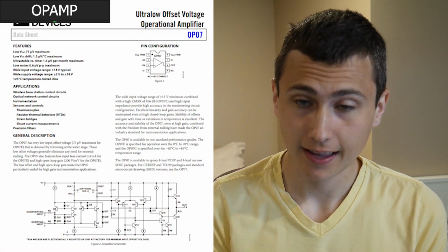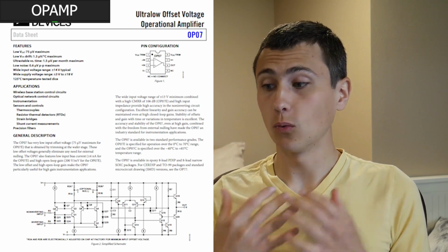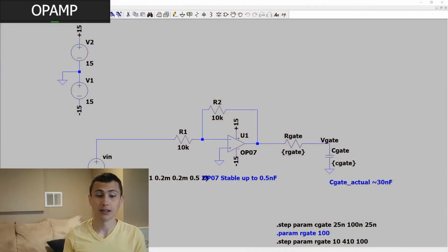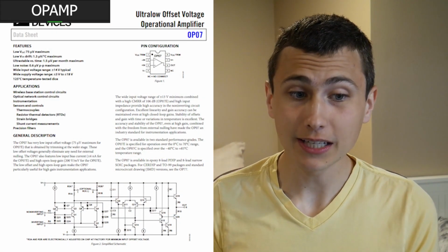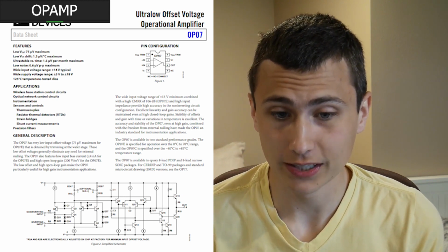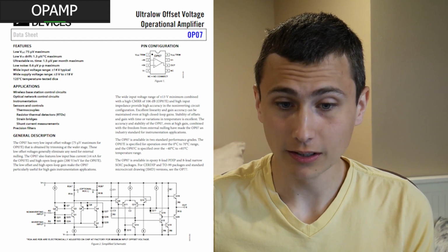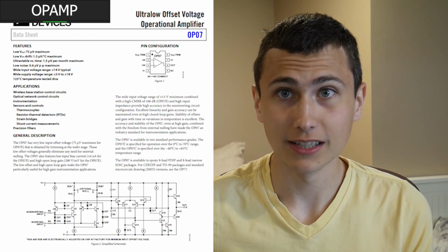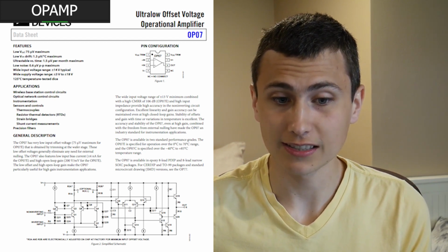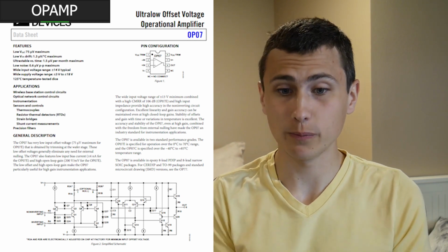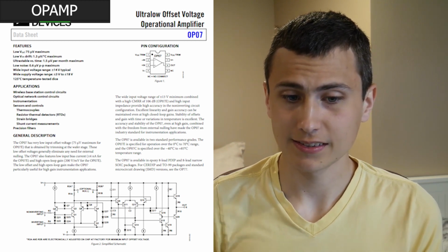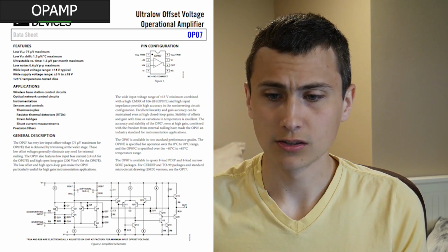The big deal about driving a part like this, you need to remember what we're driving it with, right? It's an OpAmp. It looks a lot like this. And basically what that means is there's a limited amount of output capacitance that we can drive. These parts become a little unstable. And by a little unstable, I mean very unstable. They start to oscillate if you put too much capacitance on the output. And that's not great. So we're going to need to think about that.